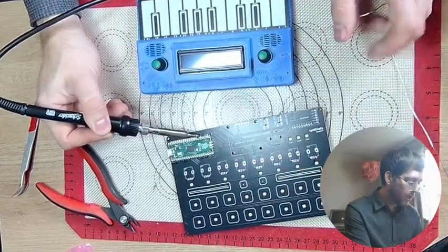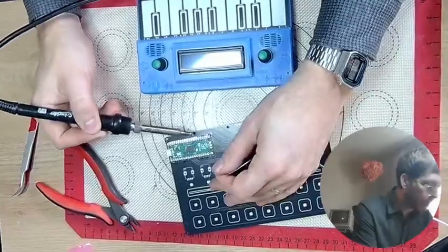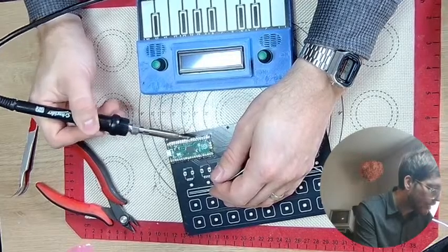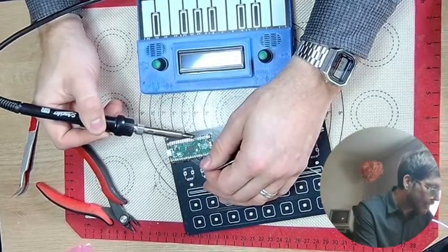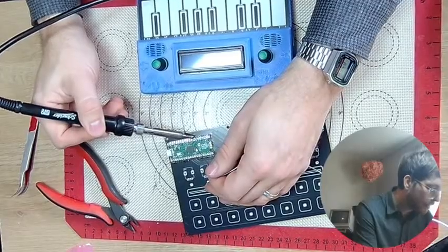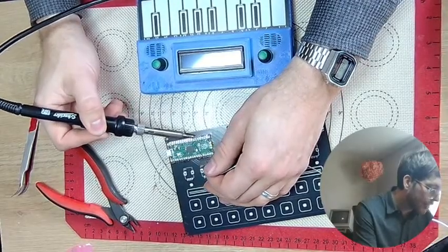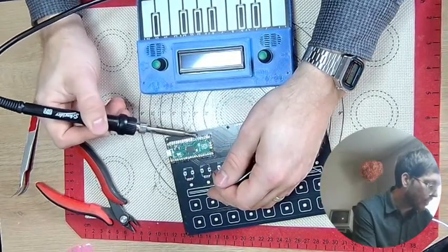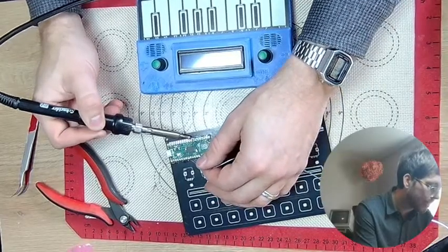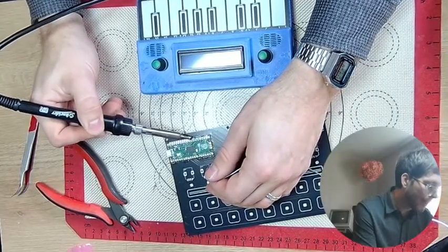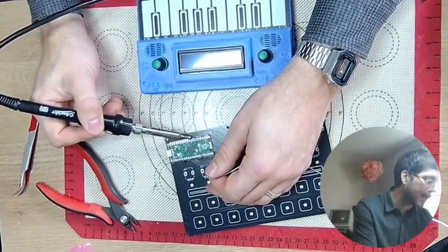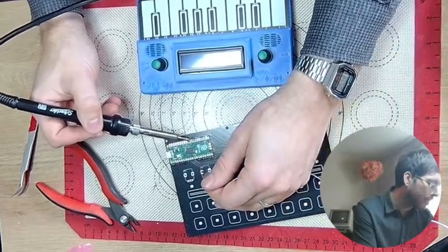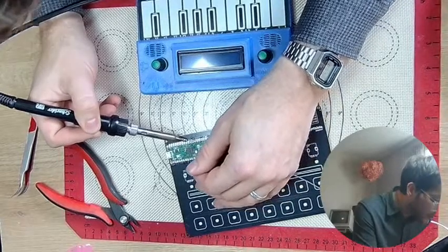Also, the screen. I don't know what came over me, but I wanted to use a 16-character 2-row display LCD, right? And that was a terrible idea because A, it uses a ton of power to light it up and everything, the backlight, and you're limited. You only have text, right? And so I couldn't show things like graphs very easily. And the refresh rate was slow. It was just a bad idea. I should have used an OLED module like this, or heck, even directly soldered one or something.